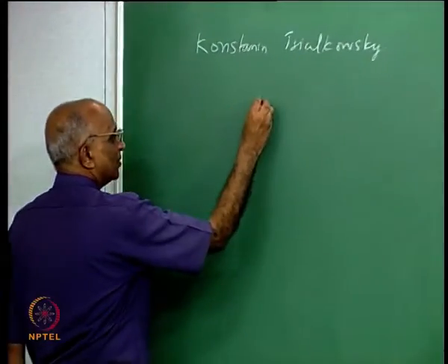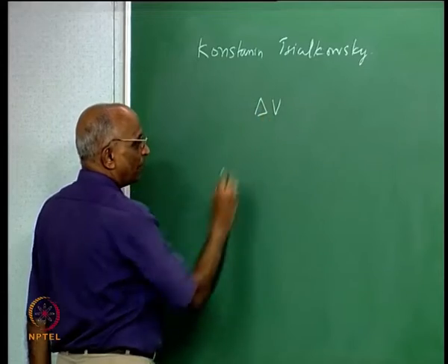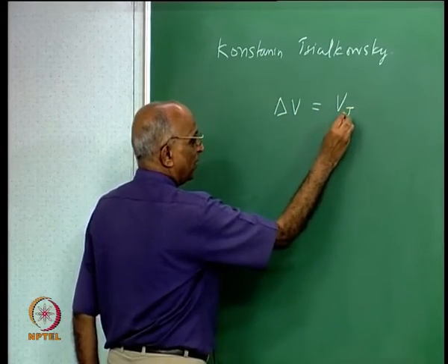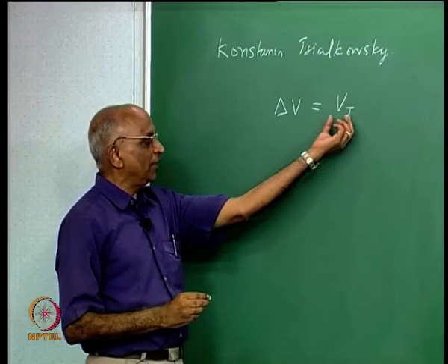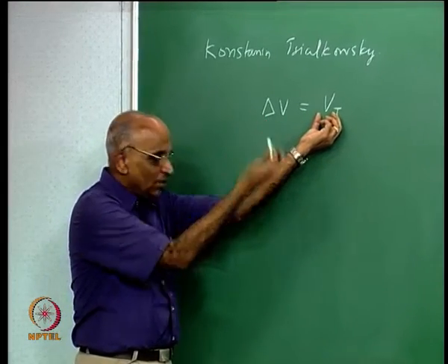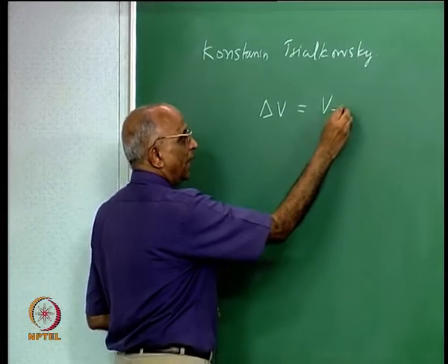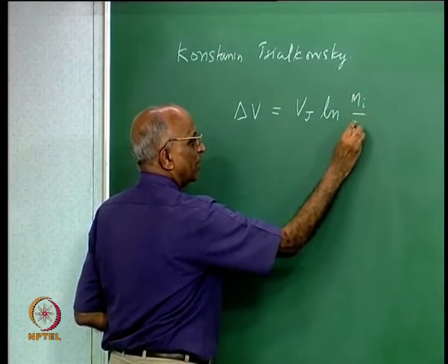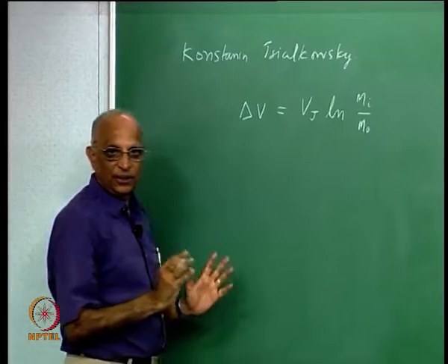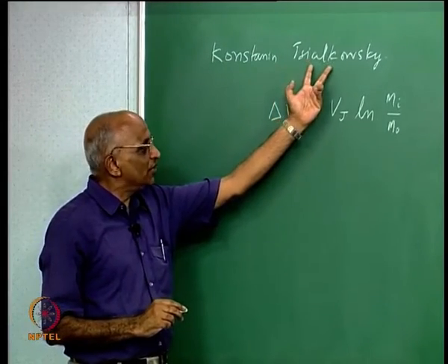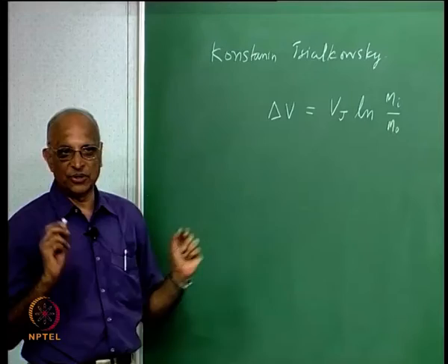The ideal velocity given by a rocket is given by the efflux velocity, or the jet velocity, that is the velocity with which the gases leave the rocket, times the logarithm of the initial mass of the rocket divided by the final mass of the rocket. This is what we call Tsiolkovsky's equation, or the rocket equation.